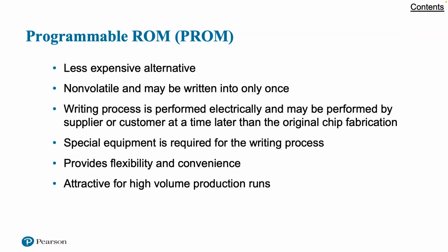For the PROM, the writing process is performed electrically and may be performed by a supplier or customer at a time later than the original chip fabrication. Special equipment is required for the writing, or, quote, programming process. PROMs provide flexibility and convenience. The ROM remains attractive for high volume production runs.